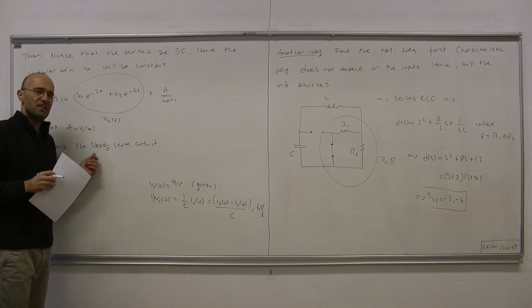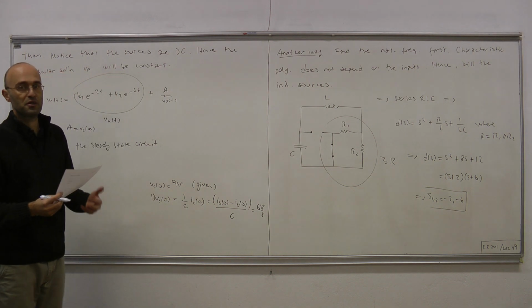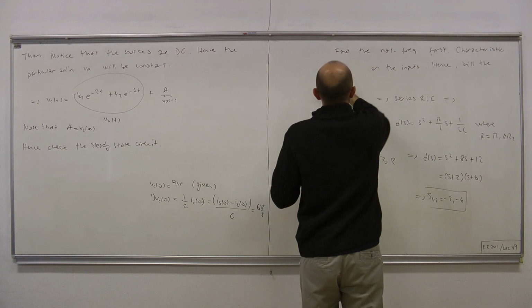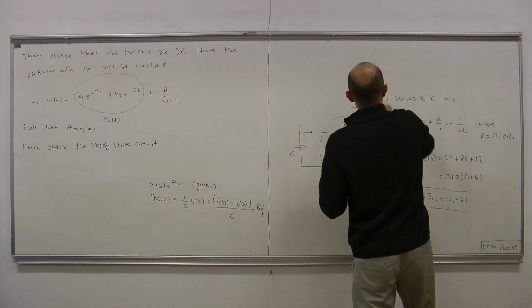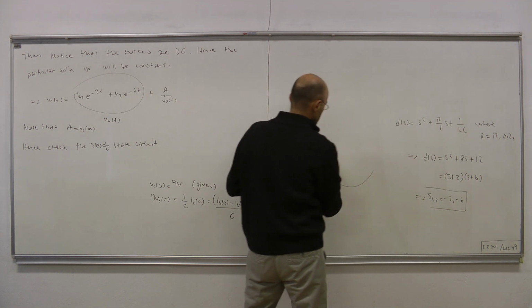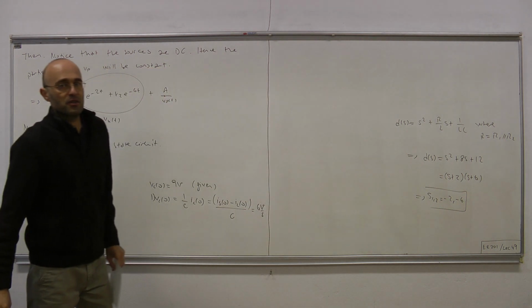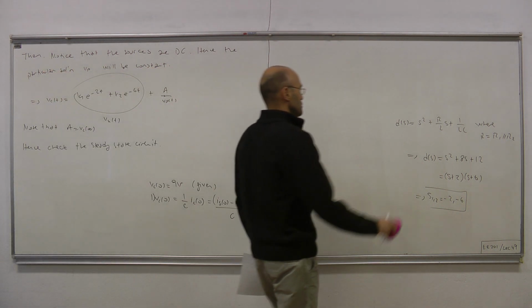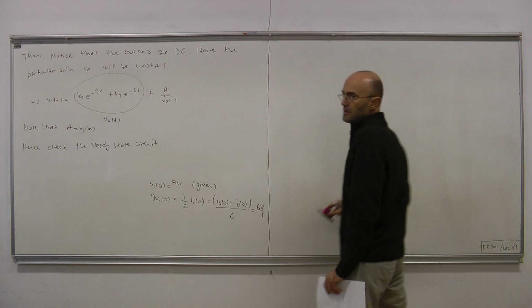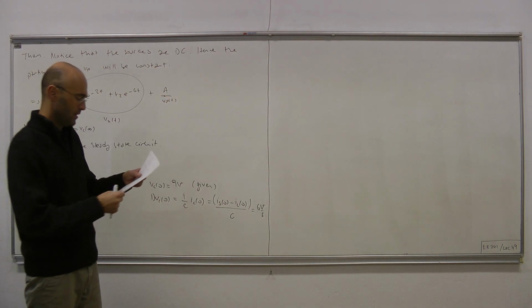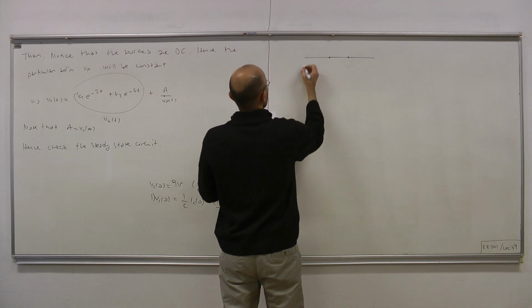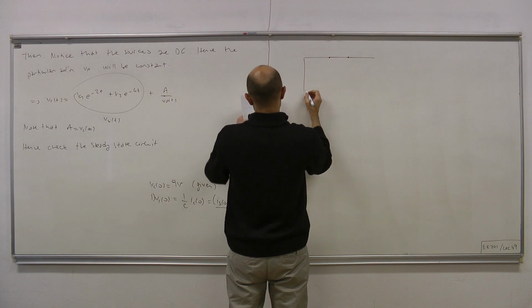Okay, we're talking about DC steady state, which we can do because the sources are constant, and we know that in DC steady state, every variable, every current and every voltage, is constant throughout the circuit. One implication of that is that the capacitor behaves like an open circuit and the inductor behaves like a short circuit in DC steady state. Using that very valuable information, we can easily compute the infinity values for capacitor voltage and inductor current.